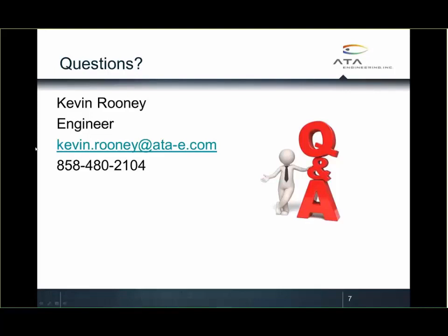All right, we have a question on the chat window about the rigid connectivity tool: if you can add nodes that weren't originally in there. Yes, that works very easily. You can just select a new node and it'll add it right into your rigid element.